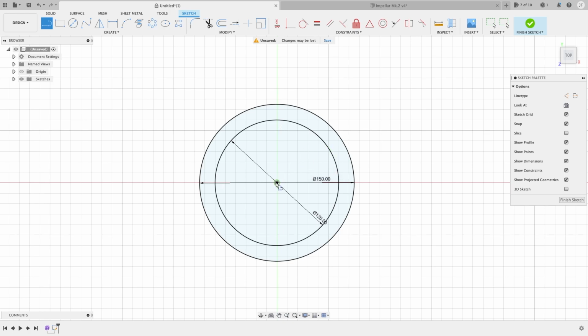We're going to do our line. We're going to click, we'll drag so it is snapped to our outer diameter here. And we're going to hit tab to keep that 75 millimeters, that is from the center to the edge of the circle. And we want to specify a certain degree for our angle. So we want it to be exactly 45 degrees. We would then type 45 degrees.